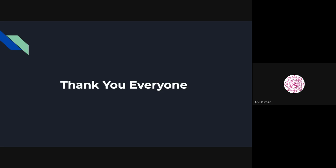So which element type did you use for bricks? Sorry, sir. What was the element type you have taken for modeling bricks in the finite element model? Sir, it's an 8 node brick. 8 node brick. Yes, sir. Okay. So you have taken one brick as one element, or you have divided that into several elements? No, sir. I took a wall as an element, as a homogeneous element for both brick and the mortar. The properties that I just said, I referred from Mr. Saroj's work and calculated accordingly.